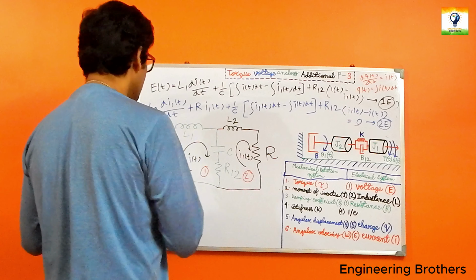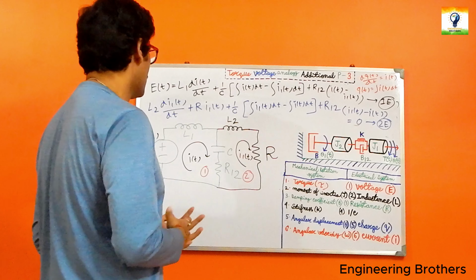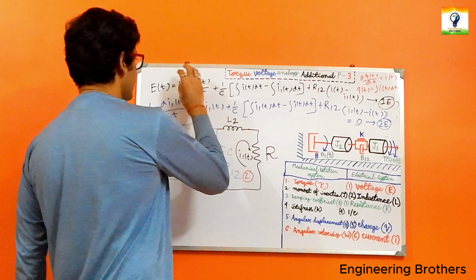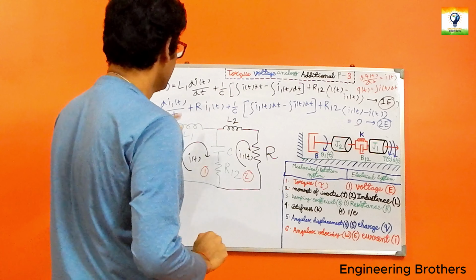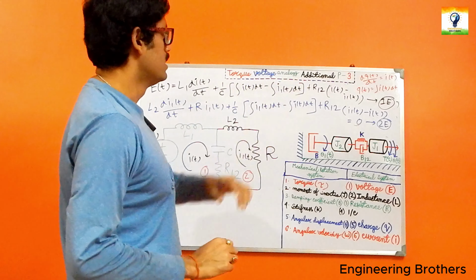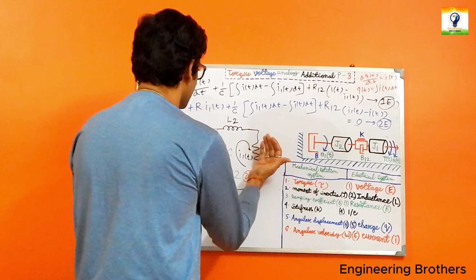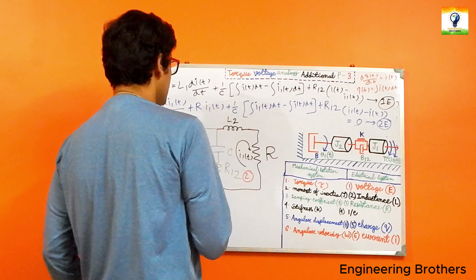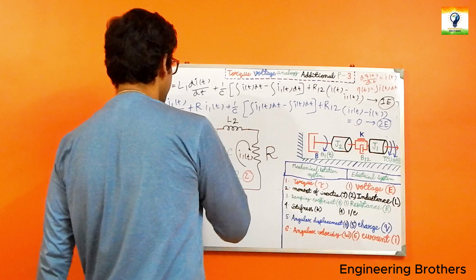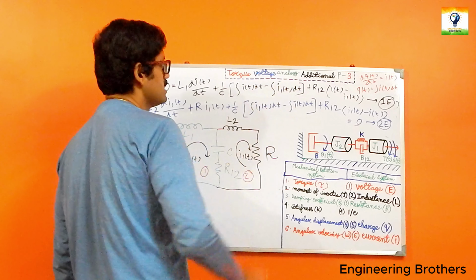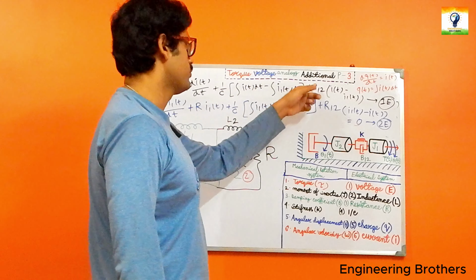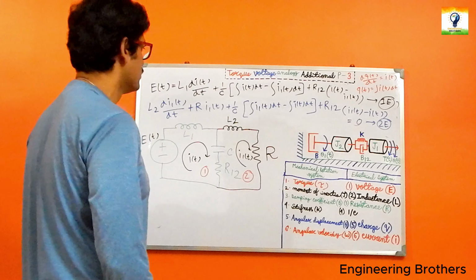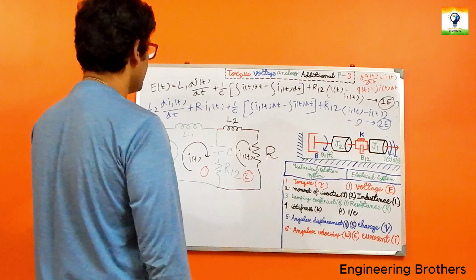So quite naturally, if you check whether our circuit is right or wrong, if you apply the KVL in this given loop, we have got ET, the voltage drop across the inductor will be L1 dIT by dt, and the capacitor and the resistor R12 are placed in between our two current elements of IT and I1T over here, and because of that, the resultant current will be IT minus I1T, and for R12 also, the difference of IT and I1T is considered over here. Now let us go to the next part of our equation.